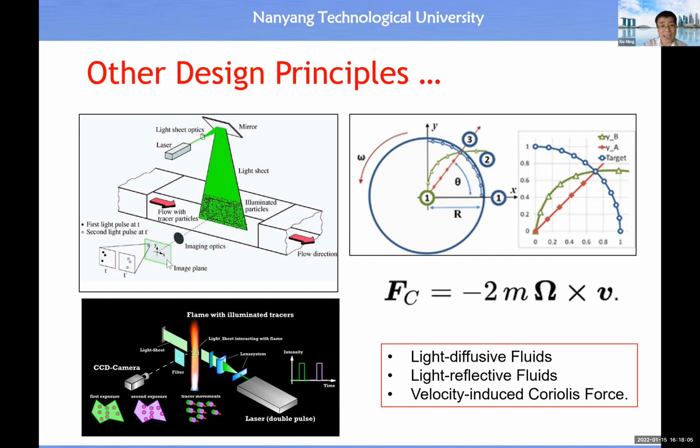Then we use a camera to capture an image at T1 and an image at T2. Then you will see we are able to estimate the velocity in the image plane. Then from the knowledge about the parameters of the camera, we should be able to calculate the velocity of the fluid. So here is one more example. At time T1, we capture this image. At time T2, we capture this image. We superimpose them together. Then you see the images of the particles moving in the image plane. And this velocity is related to the velocity of the flow.